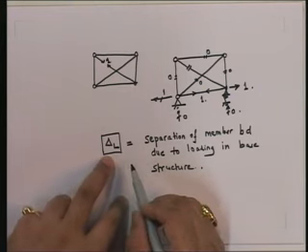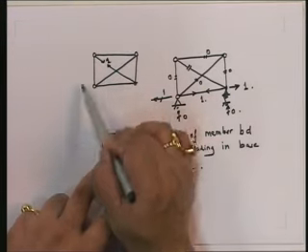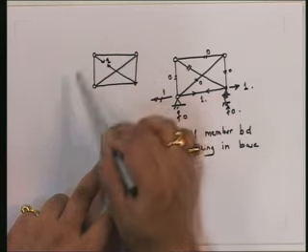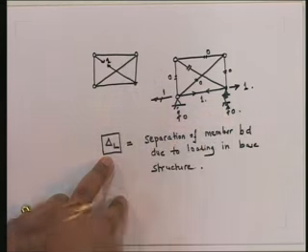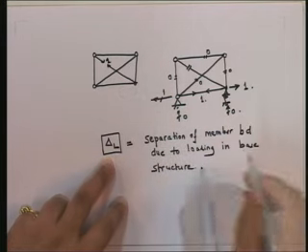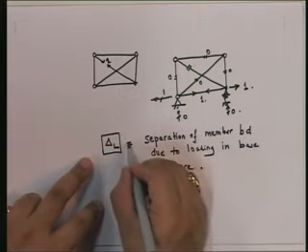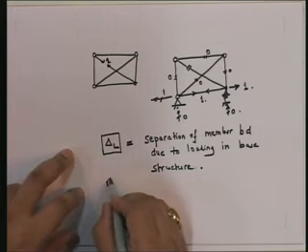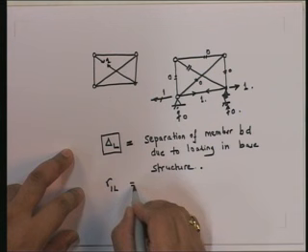How do I find this out? Well, I'd find out the forces in all the members due to this, the virtual forces, and multiply them with the real deformations due to the loading. We've already got this earlier. There's no difference in this particular case. The next thing that I'm going to find out is R1 due to L.